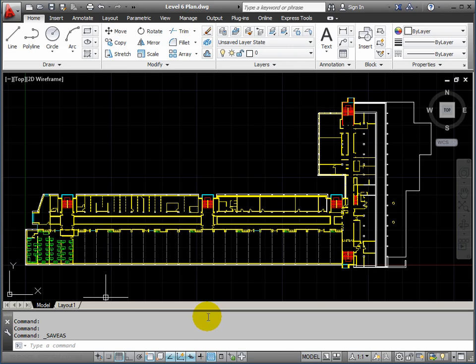Okay, below that we've got the command prompt. If your command prompt disappears completely, you can use Control and 9 to bring it back. You can also type in command prompt. Sometimes it does decide to go AWOL completely. I've also seen quite a few people park their command prompt below their Windows taskbar. Now you have to unlock the taskbar, move it to the side to bring back your command prompt. It can get dragged too far down the screen.